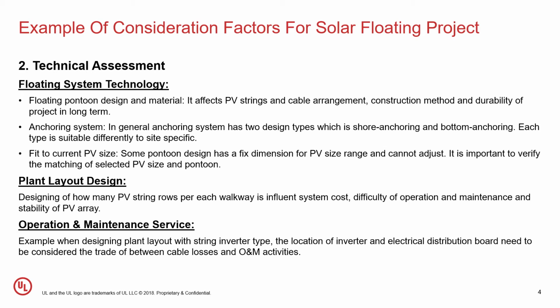And the last one for technical assessment is about operation and maintenance service. For example, if you have a project with string inverter types, you have a choice to put the inverter onshore or offshore. If you put the inverter onshore, it will be easier for O&M personnel to isolate the system when they have any emergency accident, but you have to trade off with the cable losses.